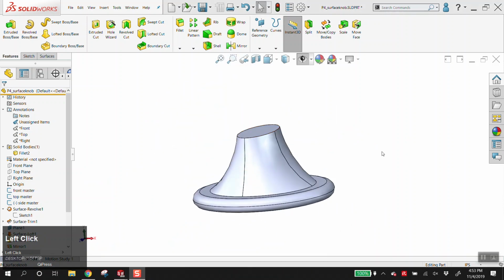Good question. Yes, in general you always want to turn a surface body back to a solid. When it comes to 3D printing, when it comes to rendering, I believe solid bodies are preferred. And sometimes you want to check mass. I mean, it depends. If you're doing rough design CAD, sometimes it's okay to leave it as a surface if all you need is the outer render. But it's best practice to return to a solid body.